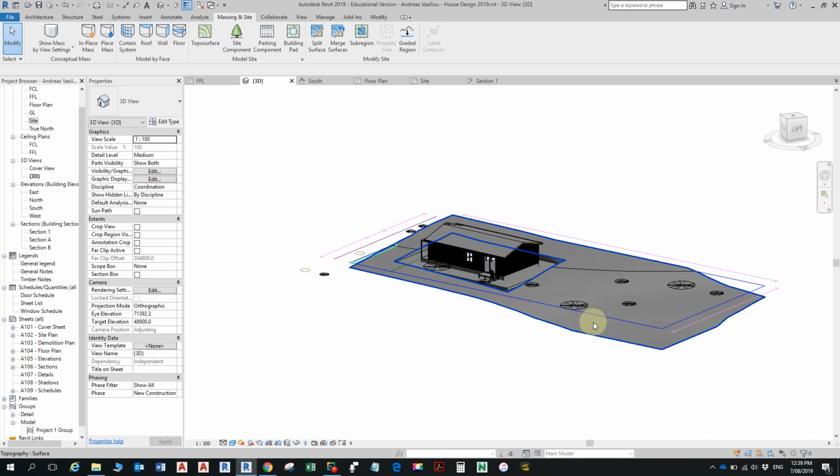So another thing, if you're going to be thinking about driveways and creating slopes and things like that, you've got to really keep in mind all the time, where is your water going to go? Councils always prefer stuff to go to the street water table. So you've got to think about your curb height and if water can go back there. On the opposite spectrum, what they really dislike is whenever stormwater goes onto someone else's property.